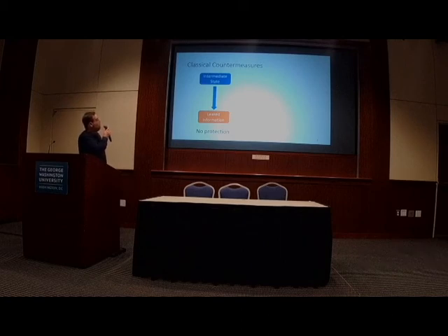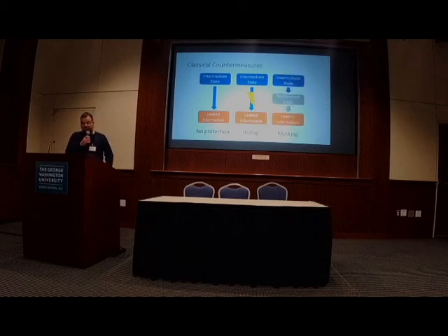Essentially, and this is motivated by the way the attacks work, we are trying to look at leaked information from intermediate states. Typically, there's a long computation going on, and the attacker focuses on one area of the computation to extract keys. If there's no protection, this is a rather easy process, but we have techniques such as hiding and masking. These are the two most popular techniques.